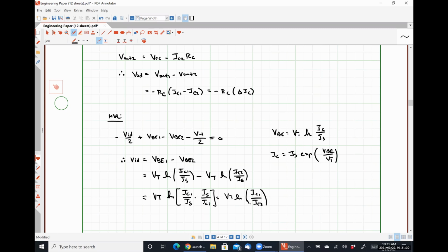It only works if we have near perfect matching between those two transistors. If we were trying to make a differential pair out of discrete transistors, generally speaking, it's going to work like hot garbage, and we're going to see lots of common mode amplification, which means everything we're doing here is bad. But if we are designing a system from the semiconductor wafer up, this is a perfect way to go about things. All right.